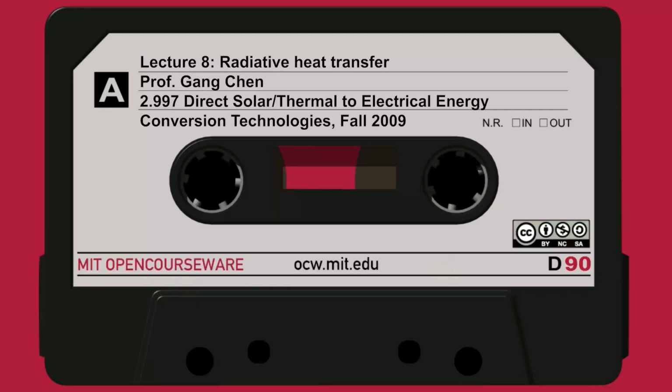So you try to do multi-junction cells, which people have reached about 41% with 3 junctions. With infinite junctions you can get to 85%, but growing material to more than 3 junctions is very difficult. Now we transform this difficulty into another one. If I can have a really ideal selective surface that works at a high temperature, then I can potentially get high efficiency even with single junctions.